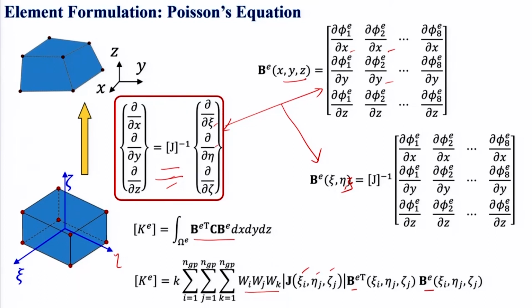Once we have the element level equation, next is the globalization of the equation, assembling all these equations to get the global matrix. This procedure is exactly the same. The assembling needs to be done based on the connectivity of the elements. Once we have the global matrix, applying the boundary conditions, getting the partitioned matrix, the corresponding condensed equations and their solution, everything will be exactly the same.